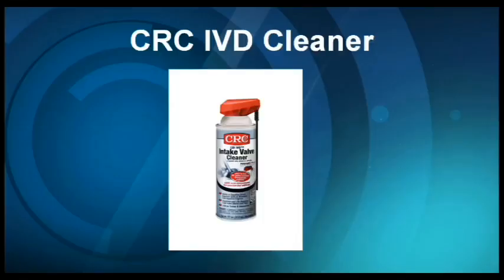Then we're going to keep the vehicle overnight and make sure that we've got rid of the customer complaint, the hesitation, and cold engine misfires. The directions on the CRC IVD cleaner tell you to administer the cleaning spray behind the mass airflow sensor. Obviously, we don't want the cleaner hitting the hot wires or the hot film in a mass airflow sensor. But wait a minute, this 2015 Mustang is EcoBoost. It does not have a mass airflow sensor.